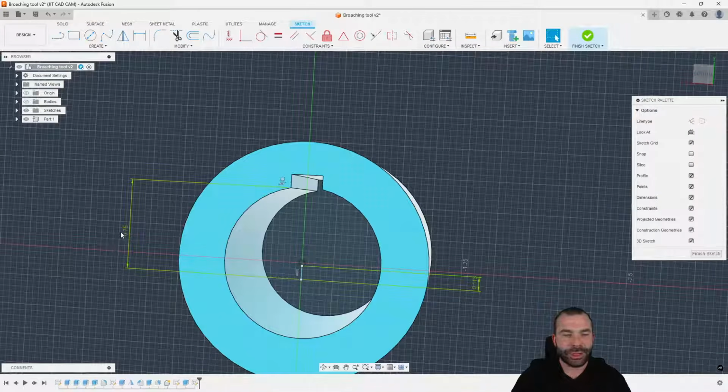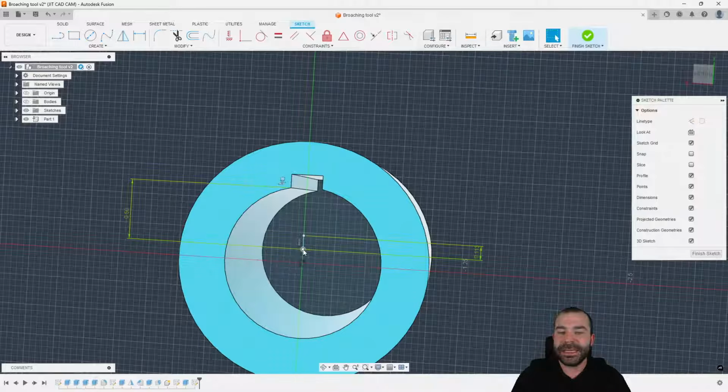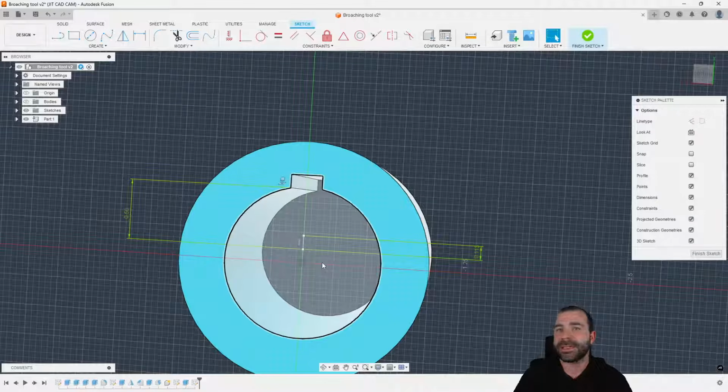Now, again, I'm going to change this one more time because obviously I'm not fitting a tool that size in there, so let's bump this down. Again, the key element here is I'm creating a point to start my path from. Now, again, you don't need the line as you did, but some of you may want a finishing pass or a final pass that you can adjust and make that a much tighter fit or open it up based on your tolerances.